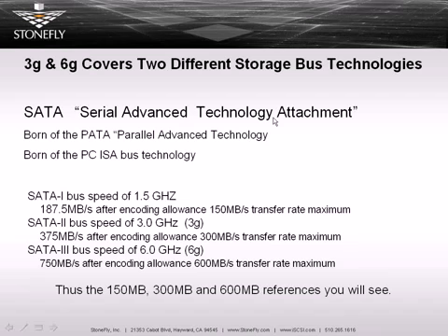All right. I mentioned SATA. SATA stands for Serial Advanced Technology Attachment, and it's born of the old parallel ATA. That was actually born of the old PC ISA bus technologies. You had controllers that had to convert from the PC bus to a command structure to drives for old standards such as ISA and ST506.